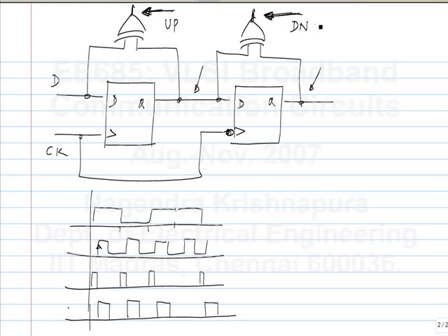So first of all, in this case, where is the reference? The reference is the data, right? So these considerations are different for a frequency synthesizer and for a clock and data recovery circuit. In a frequency synthesizer, you are trying to get a purely periodic signal without any disturbances. So you don't want the reference feedthrough. In this case, it is true, so in steady state, there are disturbances. So you would like to maybe avoid it, but in this case, it's not as critical because the input is data and you are supposed to align the clock with respect to the data.